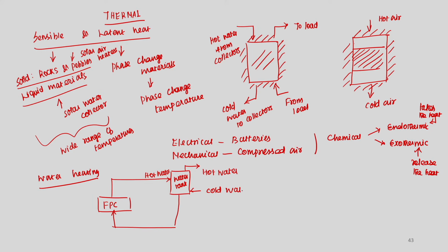So, you would fill it with the cold water. So, this works in natural circulation mode, right, but you can do it with forced circulation as well. The same arrangement: you would have the FPC, your hot water goes to the tank, and you would have provision for cold water replacement, and if you want you can use an auxiliary heater as well.